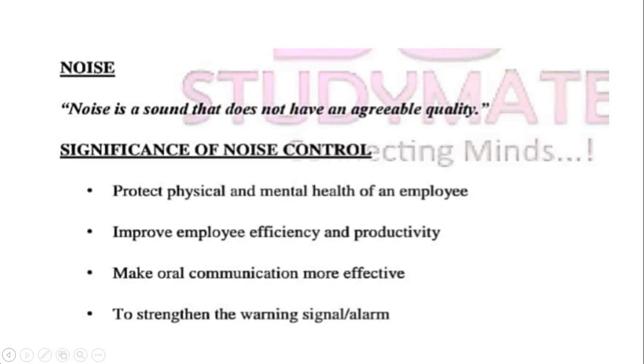Before completing this, I'll give an example. The noise level from a pneumatic drill can be reduced by placing a sound reducing blanket around the drill. A length of tubing on the exhaust of the drill will also reduce the noise level. A rubber covering can be used to reduce noise from metal falling onto metal.